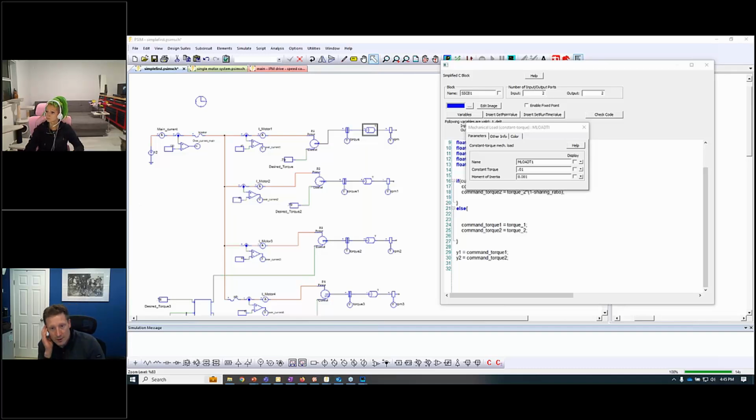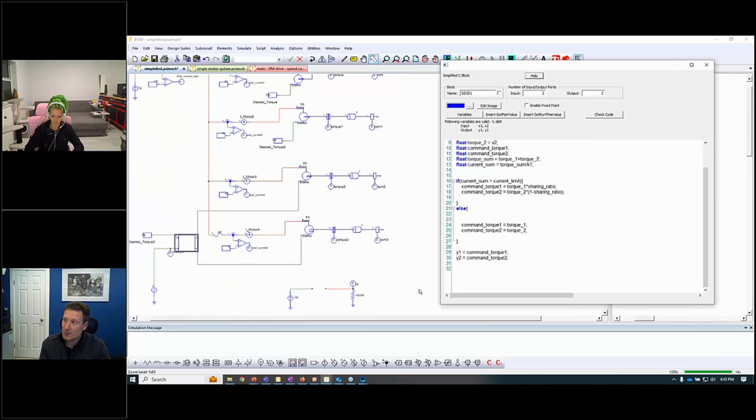To do what you're doing, what would you expect the learning time for a student to be? To do this very basic model here, you can take what I've done. These are Kraken motors that I've modeled here, with their torque constants. It should be maybe an hour to take this and put in all the motors that you're interested in. If you wanted to focus specifically on certain motors, just set some motors at arbitrarily low limits and be done with them.